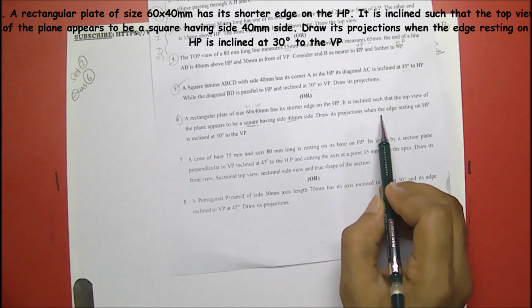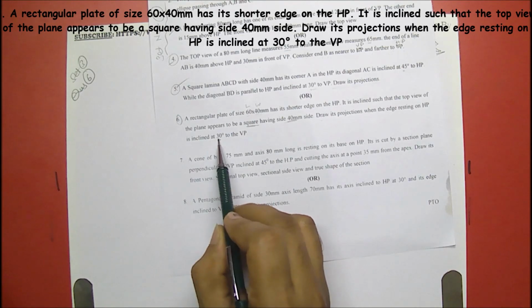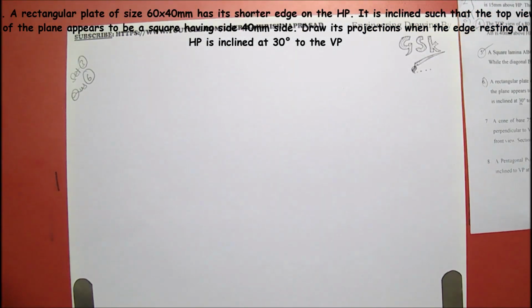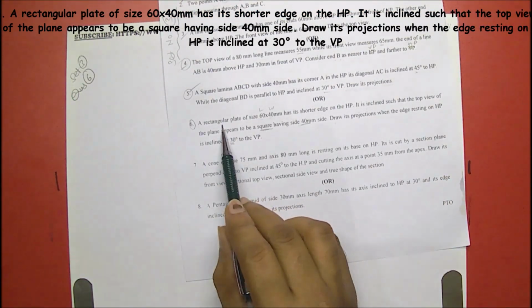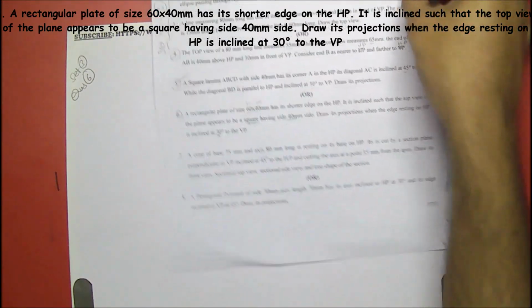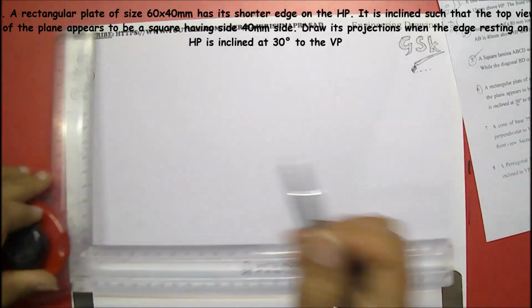Draw its projections when the edge on the HP is resting on and inclined at 30 degrees to the VP. See here, it is already given that the top view is the square and the front view is a rectangular plate of 60-40, right? Means one of the shorter edges is on HP.